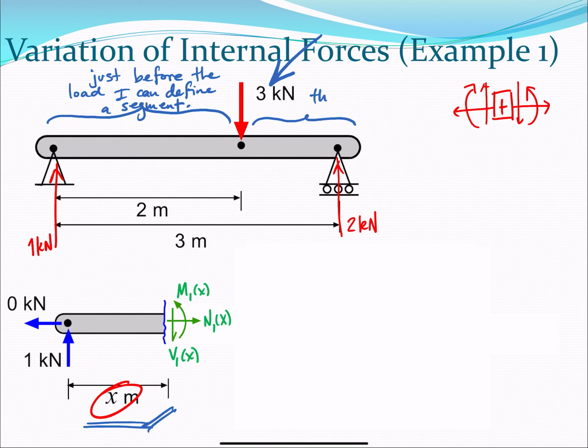So this is another segment. Every time you have a load or a reaction, or the load changes, you have another segment, and you have to define a different x. So your equations at the end are going to have brackets of applicability.